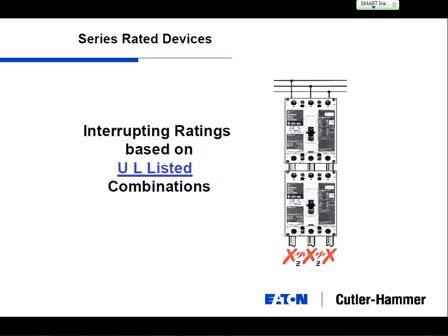The other operations tied into that same panel board can continue in their process. If you go up and trip the main breaker instead of that specific load breaker, then this little incident all of a sudden shuts down all your other operations, your critical procedures.